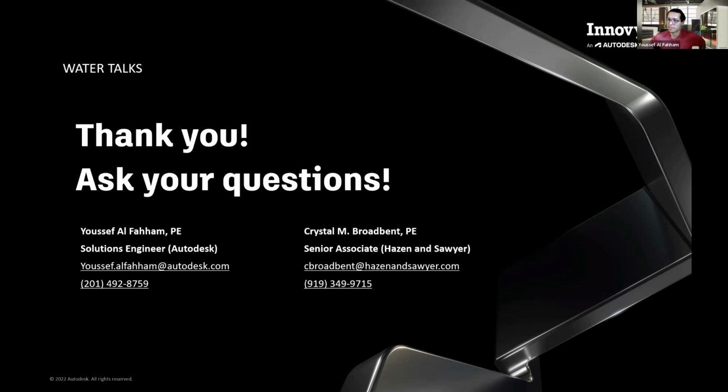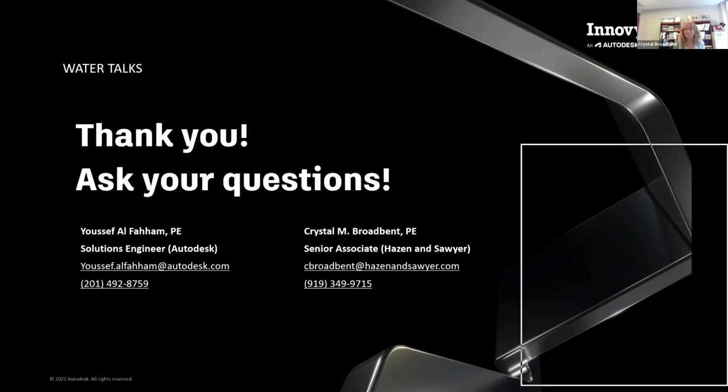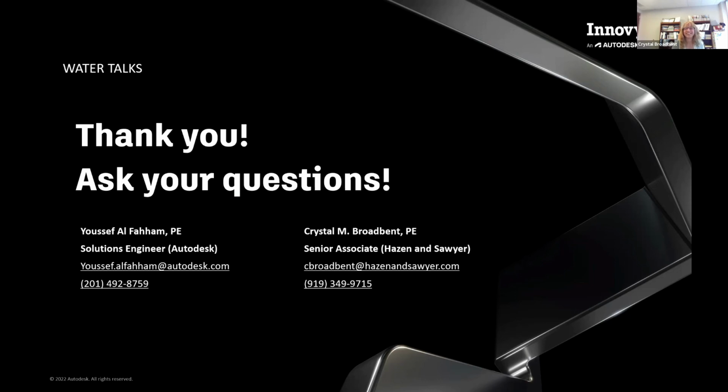Got it. And then speaking of air valves, there was a question asking, when including ARVs, air relief valves, is that managed via the active network or the physical data set? All right, so InfoSurge has one data set. It's called Surge data set. And in that data set will hold your wave speeds, your pump inertia, your control valves, your air valves, your surge relief valves, anything related to surge. There's only one data set. So when it comes to data management, there is a workaround that we have, but let's just say we're encouraging InfoWater to get us data sets. Right now, we just have separate models is how we've figured it out.